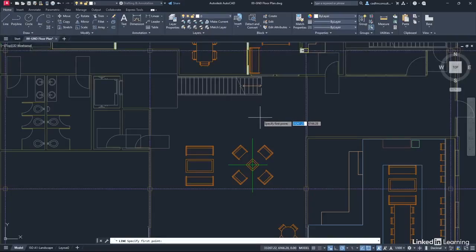Now, obviously, I've got dynamic input on, so I get a prompt for the first point of that particular line. So if I click and I drag the mouse, can you see the mouse is forming a fundamental freehand methodology of moving there. Now I can type in distances, angles, coordinates, etc. But if I just move the mouse, can you see it's allowing me to specify the direction and the angle of the line? So if I drag, say, there and left click, the mouse is now acting as a human interface device for me to click. If I come down here, left click again, another line segment. If I come down here, left click again, another line segment.